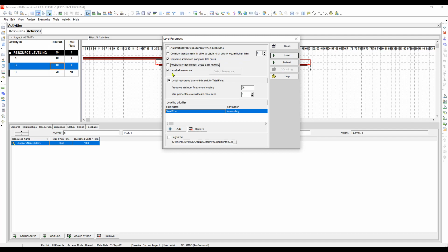Okay, label all resources. So here, even though we have a lot of resources assigned in our activity, we can choose only one. Let's say, for example, one activity has a labor assignment, a skilled personnel. If you want only the skilled personnel, then just remove this one, and then here you can select it. Okay. So if you want all of them, then check it.